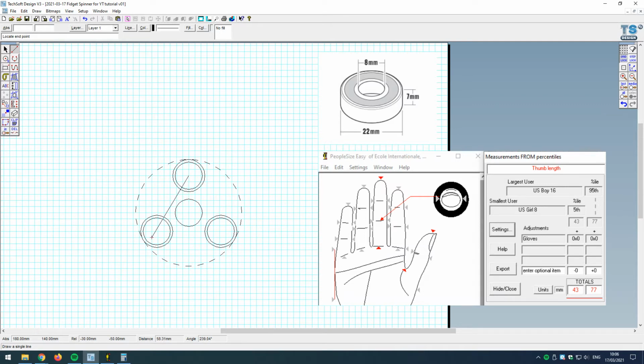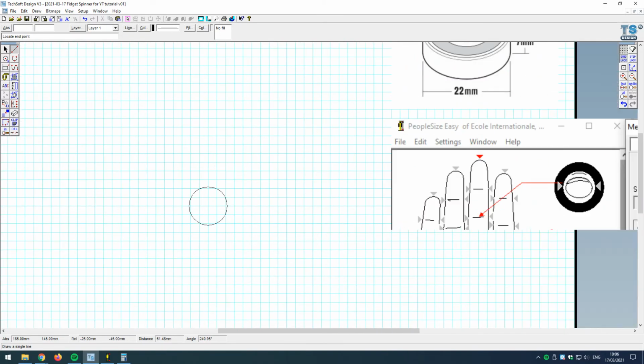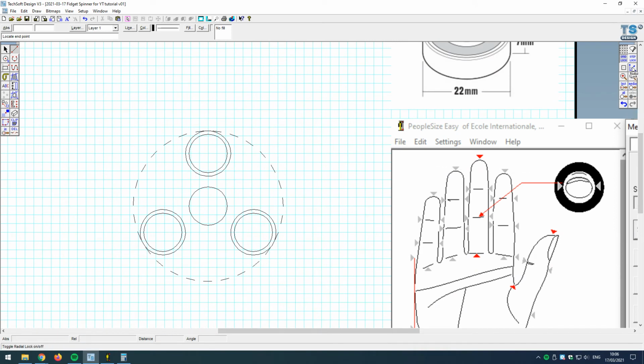And what I'm wanting to do is make it so it comes across onto the center of this bearing. But I can see here that I don't know where the center of that circle is. It certainly isn't that point there. I can see that's physically off. However, what I've got on the side here is a radial lock tool. I'm going to right click on this radial lock tool, and I'm going to define my step angle here, not as 45, which means at the moment you can see it's going from 0 to 45 to 90, 135, 180. I'm going to put this to 15 degrees increments. So now it's going 0, 15, 30, 45, 60, 75, 90, etc. And if I come down here, I can see that's actually snapping beautifully across there.